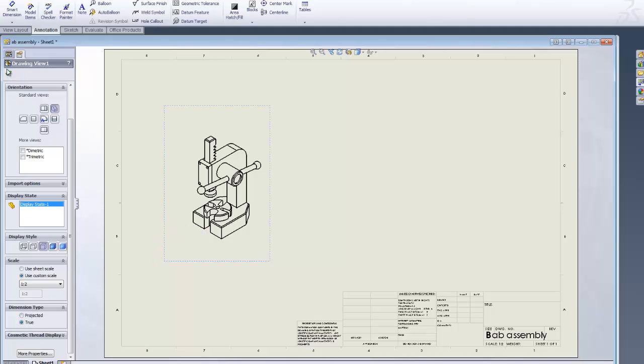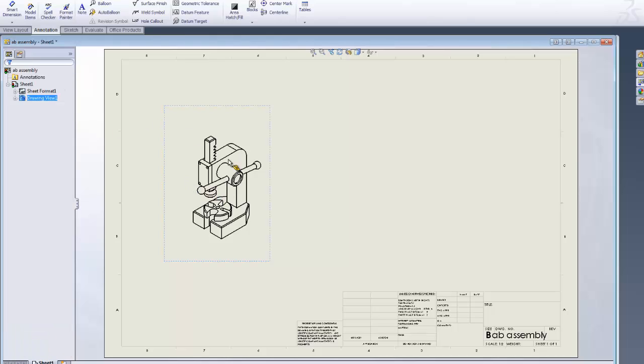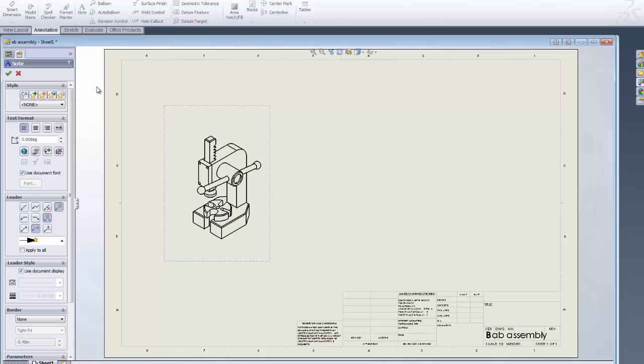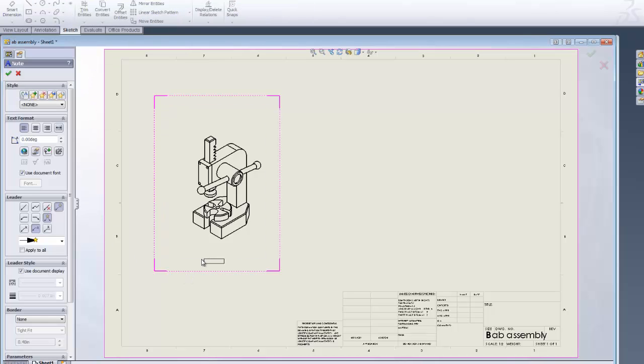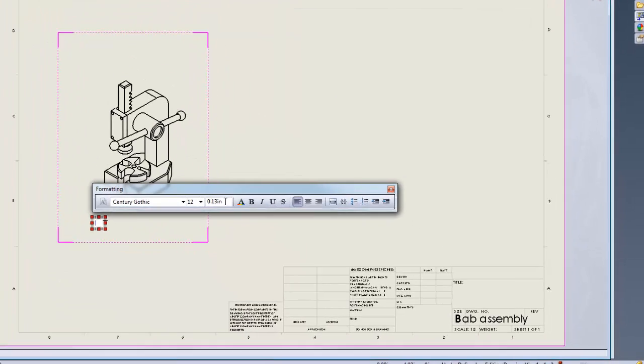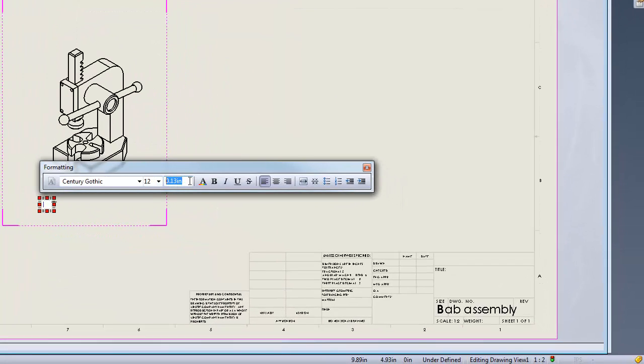Once we decide our view and we lock that in, we do need to do a few things with our assembly. First we want to put a note which will give us a chance to place a label as to what this drawing is. And it's always good to label our drawings. A drawing title is typically done at a 1/4 inch height or 0.2, and we're going to use a Gothic style lettering as we work there. And I'm just going to go ahead and type in, using all cap letters, the name of this drawing. So this is an assembly drawing.